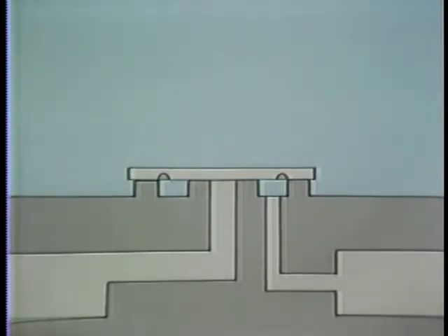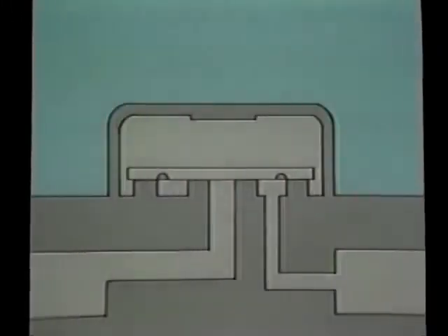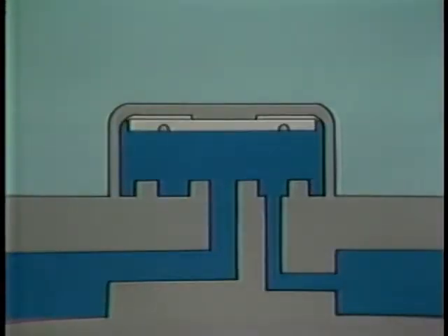The area containing the disc is called the control chamber. It is a relatively large volume space with restricted inlet and outlet ports. It is the change of state which occurs here that normally controls the opening and closing of the disc trap. On startup, condensate at the inlet port pushes the disc off the seat and flows freely to the outlet port. Condensate passing into the trap drops in pressure.